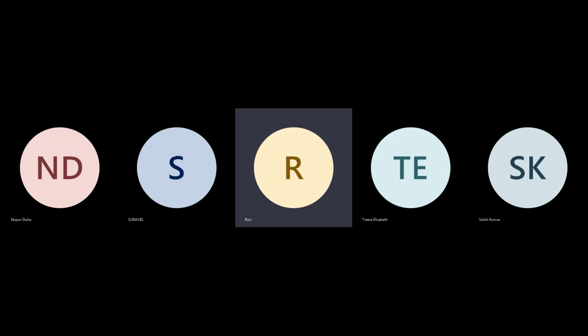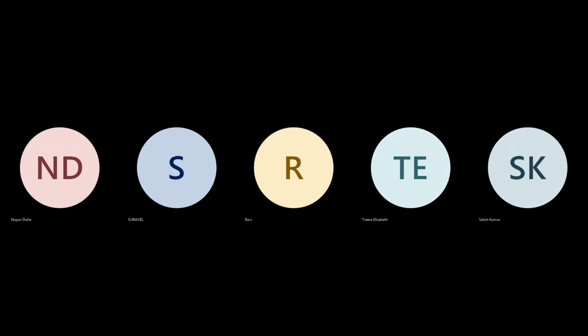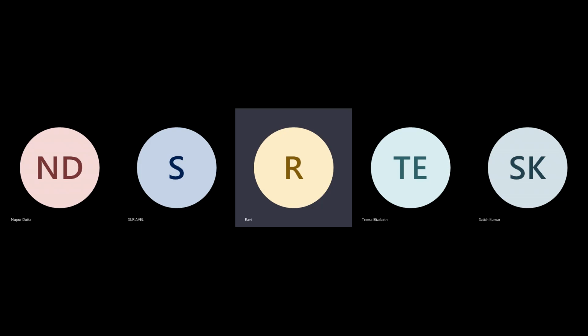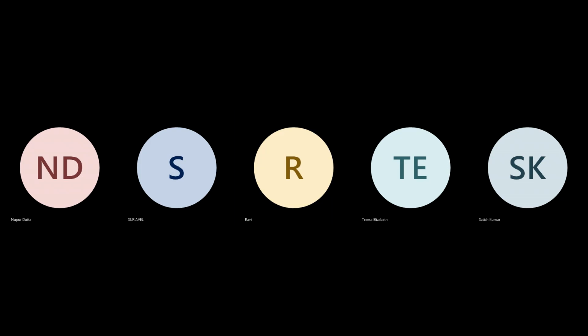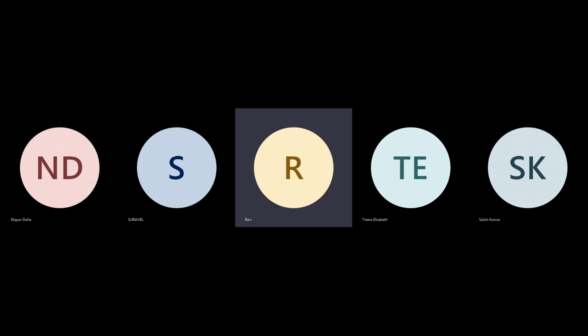So rise time is between 10% of your thing to 90%. This is what your textbook will tell. Yes, but that depends on the characterization. If the characterization is 30, 40, that's what you have to take. Okay, so I will explain all this. By default, library transition time will be taken, but you should also in addition add your frequency related stuff. So add this and run your placement.